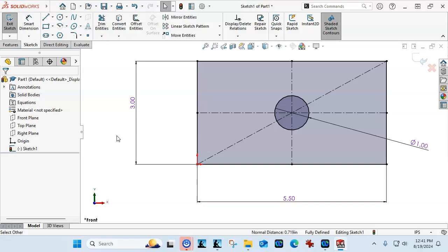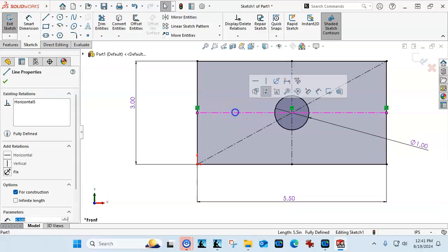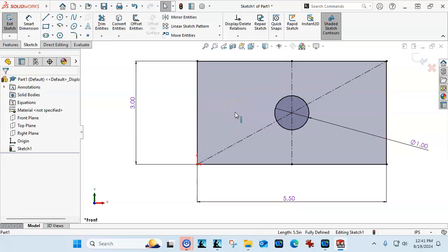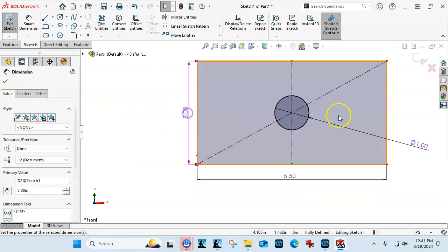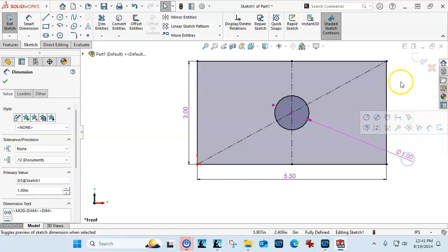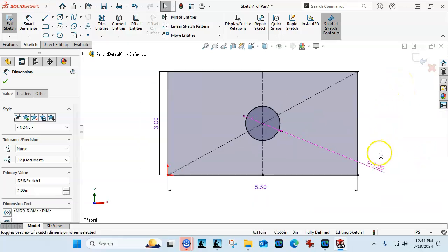All right, so this one went quite a bit faster in the process. We ended up with these extra lines. So if I wanted to get rid of one of those, I'm going to left click so that it highlights and hit delete. But if there was a dimension relation attached to it, it would warn me, hey, you're deleting something that could have a downstream effect on other geometries. So are you sure you want to do that?